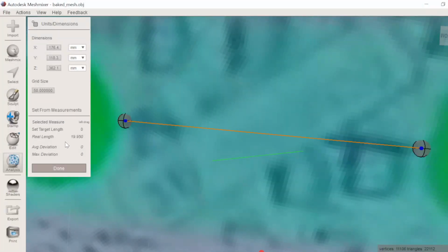We see here now scaling what is STL. I think it's not selected, also not selecting the edge correctly. So now it looks good. We see it's 20.1. For me it's fully okay, but if you like, you can set this also to 20. And now it uses the mid weight. So you see here a max deviation of 0.05 between the two.